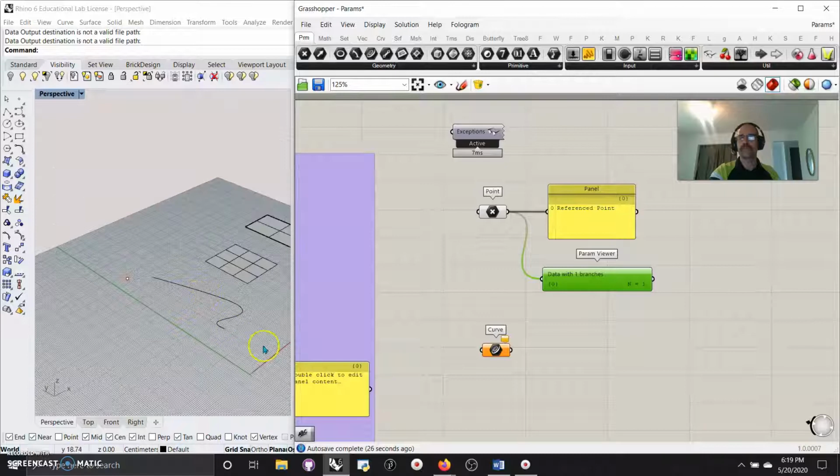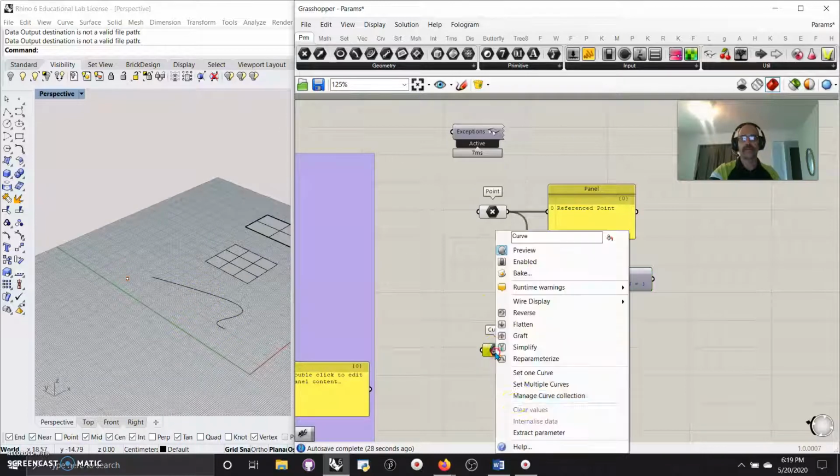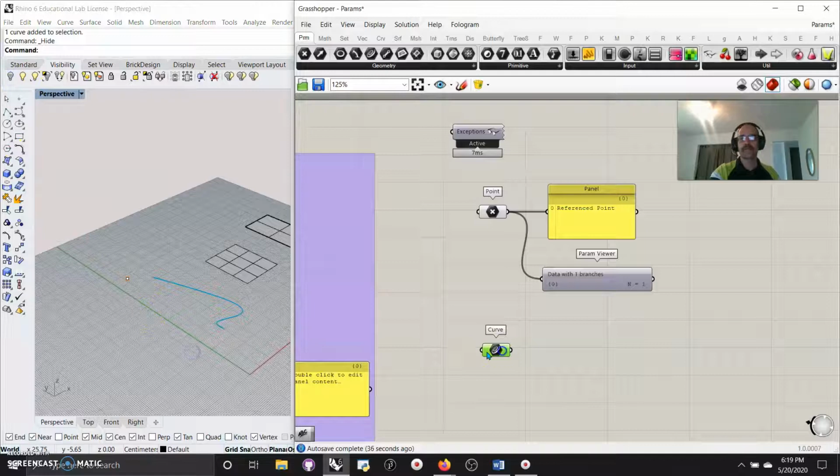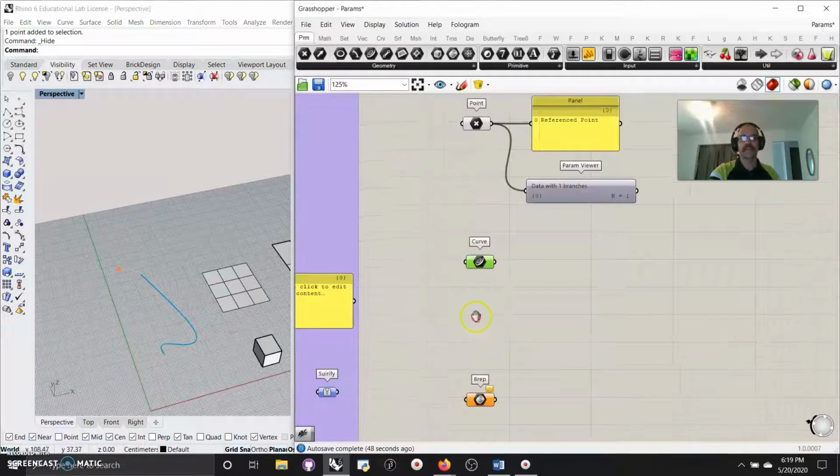We better keep moving. So let's center here. Let's grab here. Let's go over, select one curve, select that curve, and there we go. We can go back to this curve now. We can pop it into hidden, and now we have a reference point. We have a point that's in Rhino, and we have this one in Rhino. And actually, I think that little object's still not hidden yet. There we go. So you got the point that turns blue, and the Grasshopper items are orange, and there's nothing else physically there.